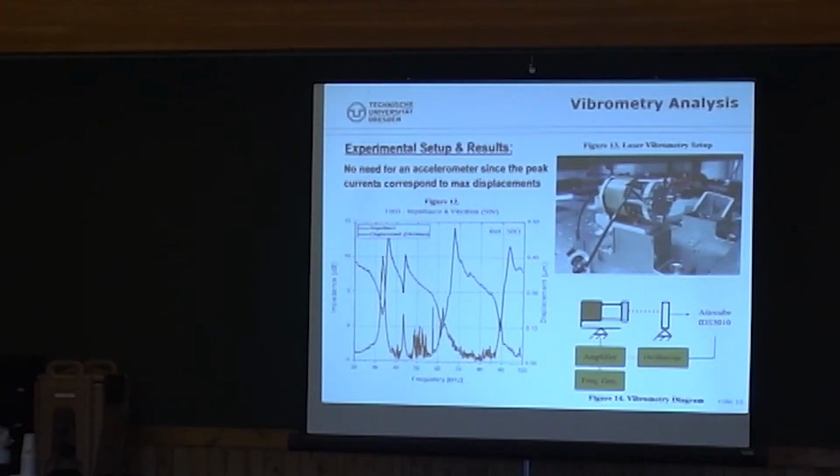So the mechanical resonance, shown by the maximal amplitude of the aluminum mass, corresponds exactly to the impedance dip. So at both of these resonance frequencies, I also have an increased amplitude in the movement of the aluminum mass. I should have explained how I did the experiment, but it's pretty straightforward.